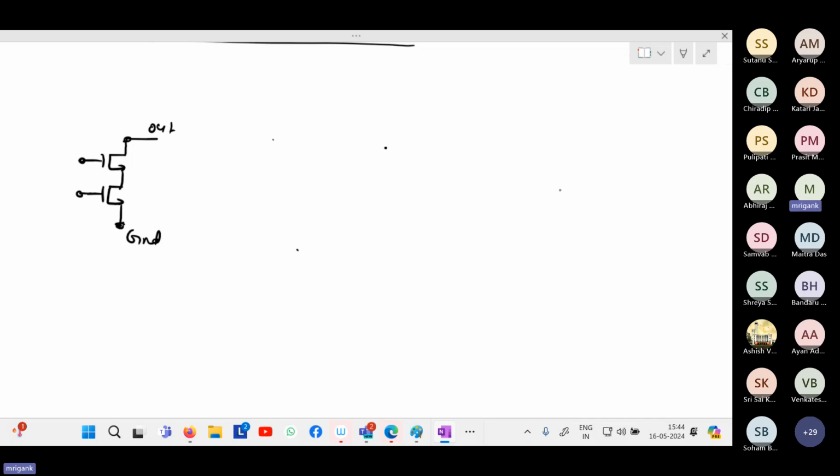Now for that, first of all, there will be two NMOSFETs. So I can draw those two NMOSFETs. Likewise, there is another NMOSFET. So these two are there, and maybe I need the body contact also. So you have P plus body contact, P plus body contact.